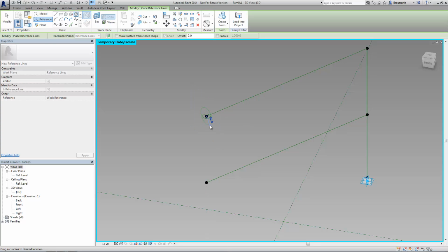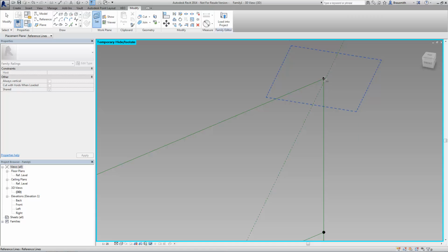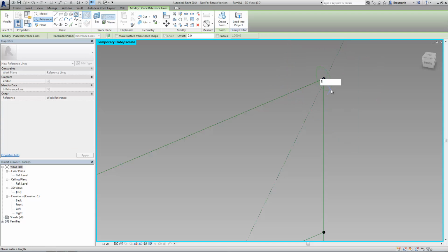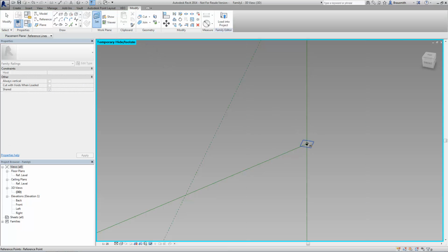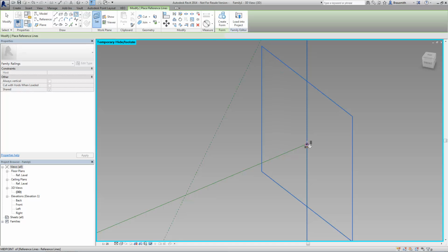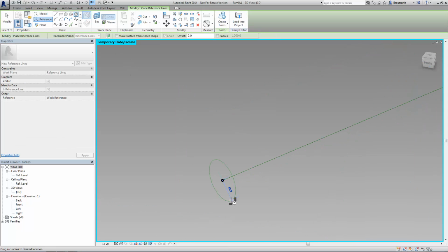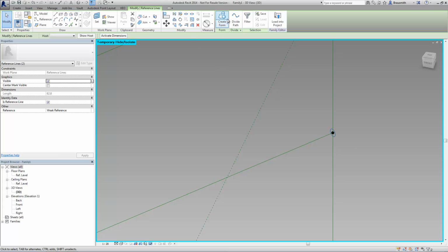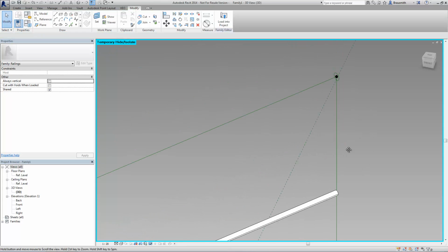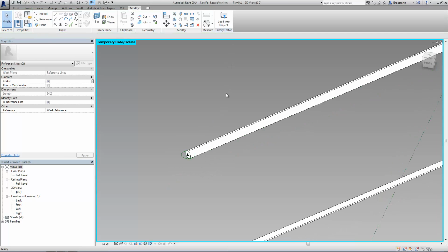This one's going to be 15 mil radius. Do the same up the other end. Set work plane at the end, pick 15. While I'm here, and I've still got the reference circle still running, I'm going to do the other two ends of this line. So there, this will be 10, and back over the other side. Set, tab, select, and 10 mil. Selecting the geometry, create form, and the same again, select the geometry, which is that one, and create form.